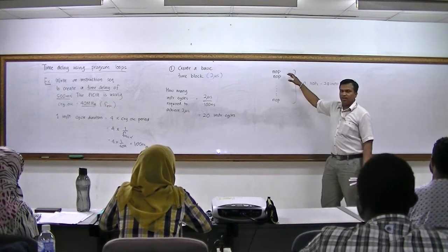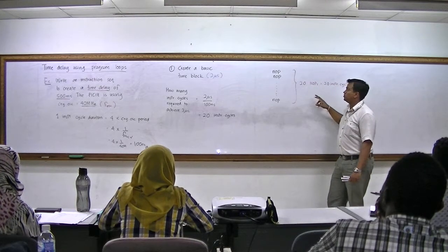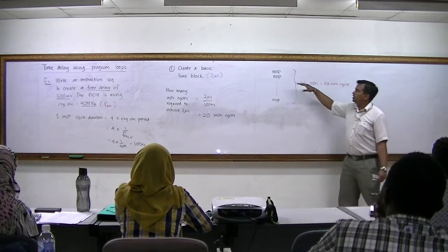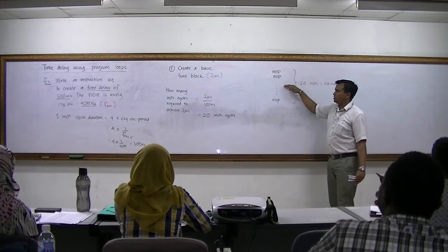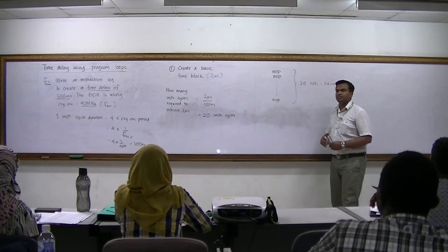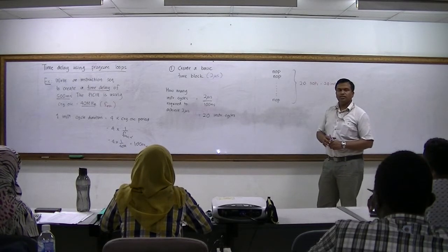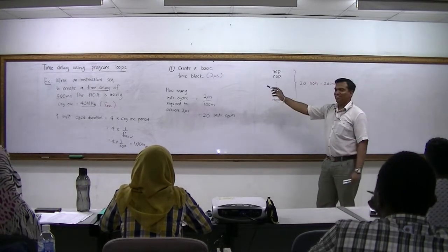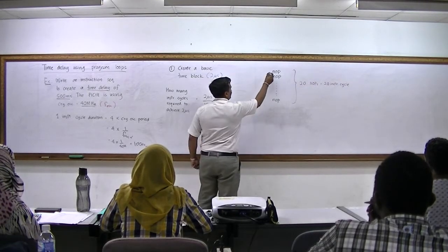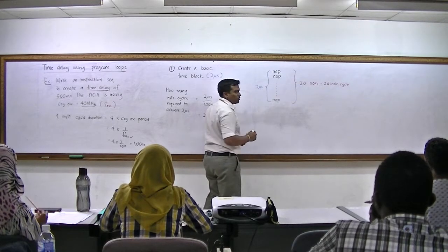So if in my program I write 20 NOPs, this whole NOP sequence equals 20 instruction cycles, right? For the PIC to execute these 20 instruction cycles, how long does it take? 2 microseconds. Just this advanced, right? So this whole thing takes a 2 microsecond delay to execute.